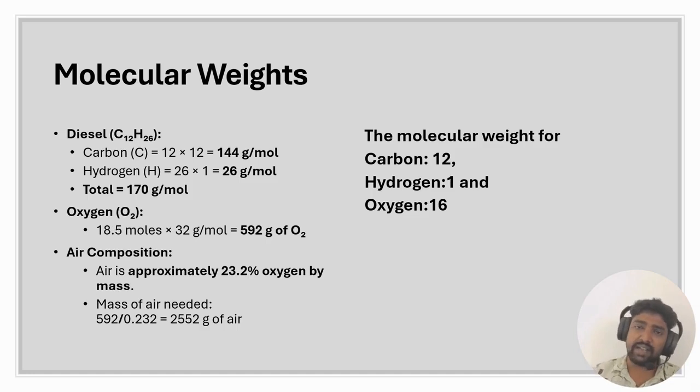The answer is that in a diesel engine, the fuel is injected into highly compressed air at the end of the compression stroke. We control the power output solely by varying the amount of fuel injected, while the amount of air drawn in per cycle remains relatively constant.